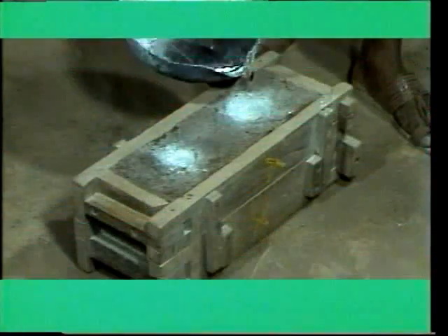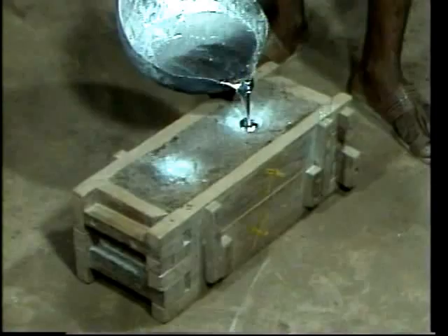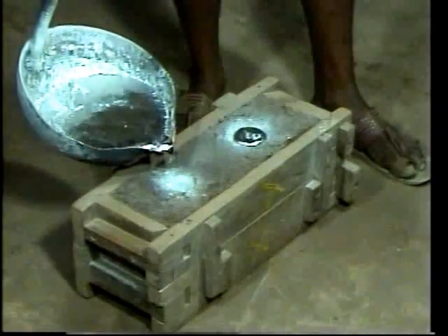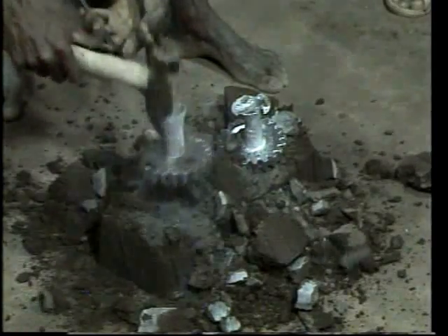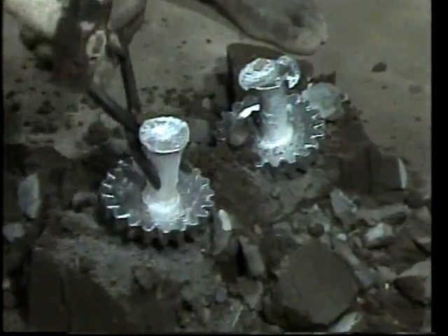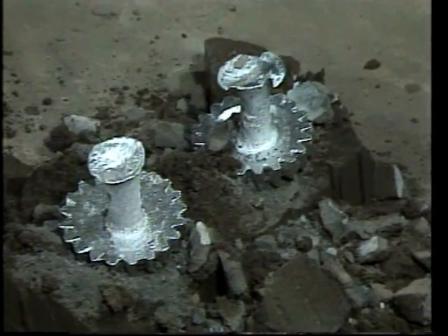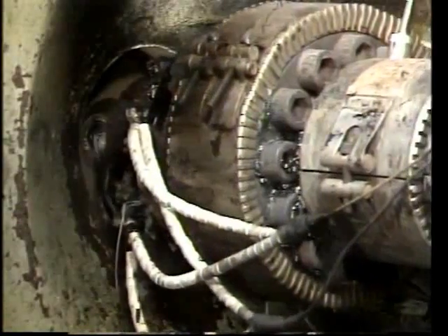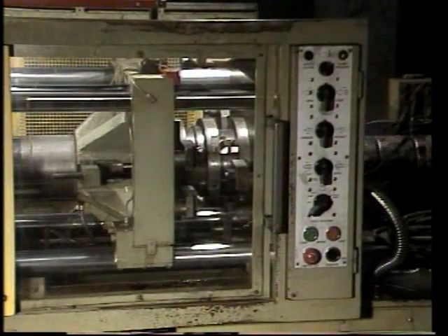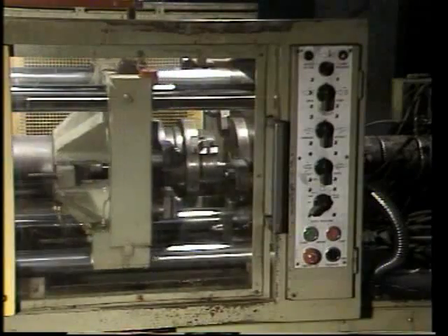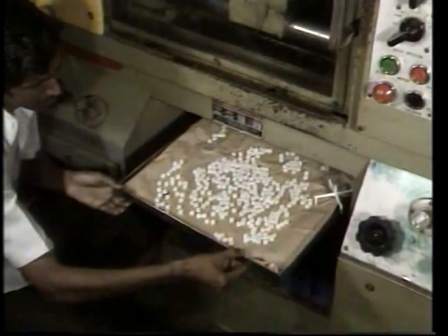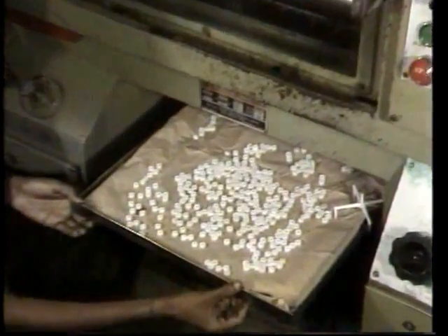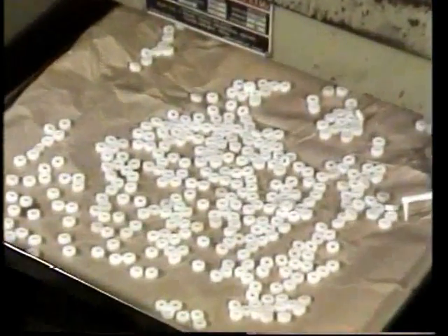Spur gears are produced by different methods. The primitive method is the sand casting process, which produces coarse quality gears. The cast gears are for slow speed applications and where high accuracy is not a prime factor. Gears are also produced from plastic materials by injection molding. This method is employed where quietness, insulating properties, and moderate strength for light surfaces are needed.